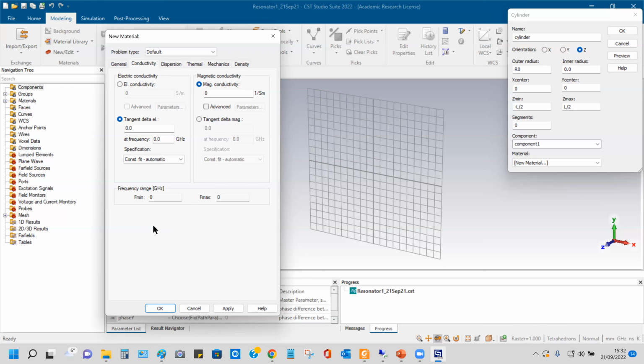And thickness also plays some role in a wider bandwidth, because you might have studied, right? Thicker substrate will give you wider bandwidth, thinner substrate will give you narrow bandwidth. Why? Because the loss tangent is calculated with the free electrons. That basically affects the substrate. Substrate is not an ideal substrate. An ideal dielectric should have zero conductivity, right?